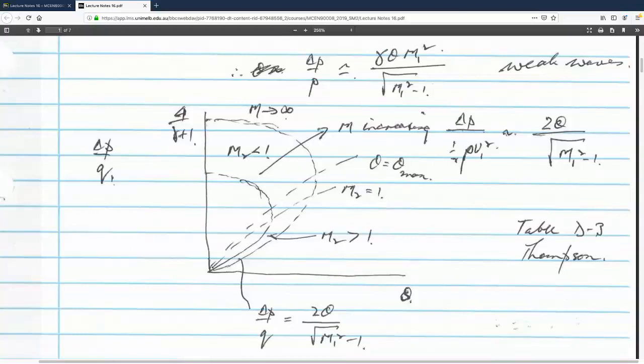It's recast into what is commonly called the shock polar, and I'm going to show you why people worry about it or use it. But it's interesting that just a small increase in angle at the critical point and the delta p over q shoots right up. I'm saying, see how you see the edge of the curve?